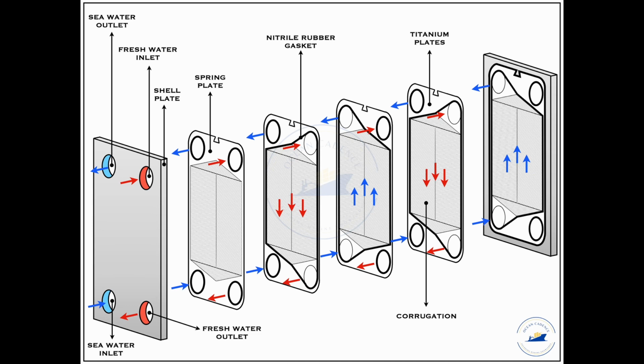Now coming back to the general plate type heat exchangers, again you can see that on the extreme plate there will be at the back side again one more cushion plate or buffer plate, and then finally the tightening plate. The frame plate and the tightening plate, that are the two extreme plates, the thicker ones, are the ones that are supposed to bear the load of the compression that is happening when we are tightening the nuts on the stud. So as we keep on tightening, the stud will move through all the plates on the sides and finally come out of both the extreme plates.